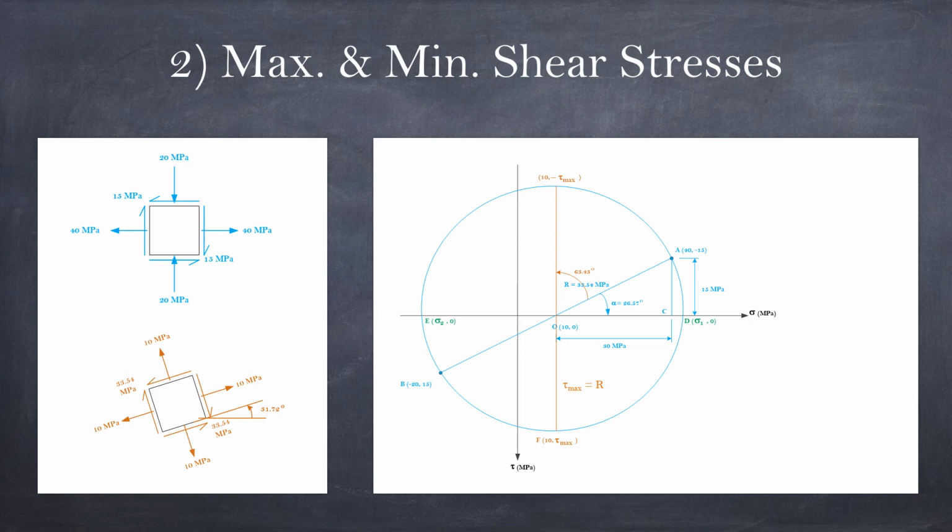In this case it is 33 something there, right? Now, notice one thing though, it is something that I have to say here. This time, the normal stress is not zero for this case, right? Because to go to the highest and lowest points of the circle, you must measure exactly on the same level, in line with the center of the circle, right? Which in this case means that the normal stress already carries a value of 10 megapascal, right? But positive though, okay?